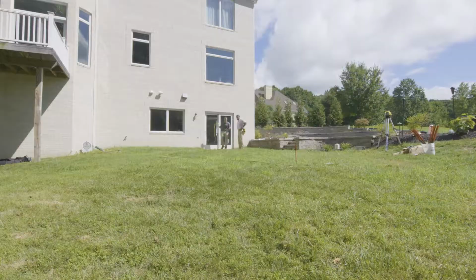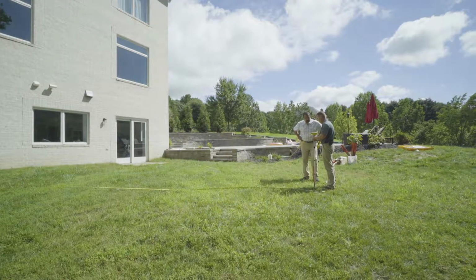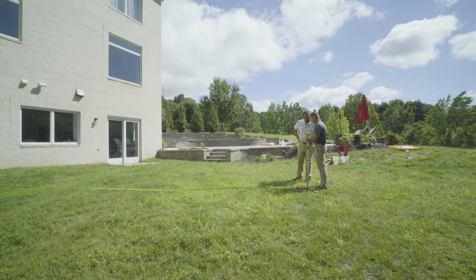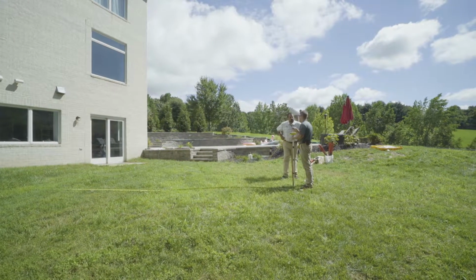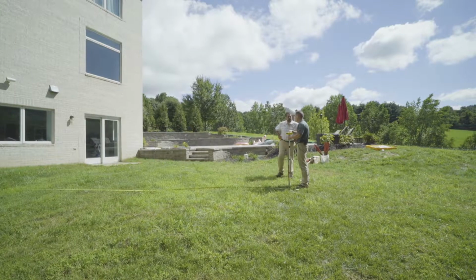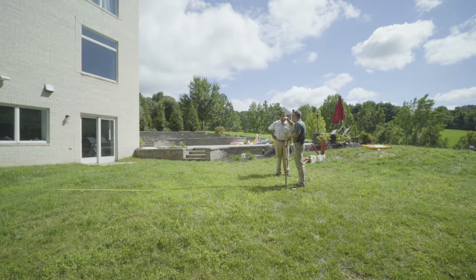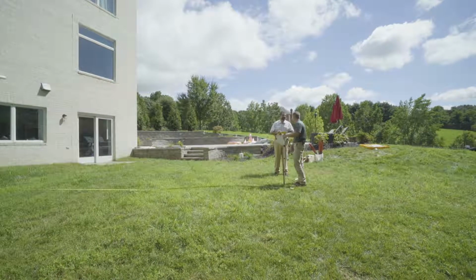Whatever elevations. Show me another one. So let's take a walk. And right now, this is coming in at right around 13.0. When it beeps, it hits it. So I'm about 13 inches lower here than I am there. So we're going to have a cut line here because we have to go deeper.